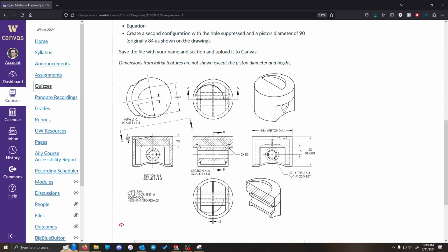Another thing to keep an eye out for is holes. If a hole is done before the shell, then the entire pathway of the hole is going to have a thickness associated with it. Continuing on in that front view, we have hatched solid material that our section is cutting through on the top and bottom of our hole as it passes through our object. Because we see that thickness, the hole needs to happen before the shell. If the hole happens after the shell, we're going to end up with a cutout on the right side and a cutout on the left side, but it will just be empty open space in the middle and we won't have that tube acting as a guide.